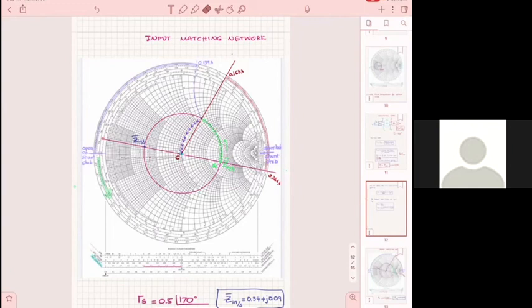That's why, moving in one direction or another, it's a good thing in practice to always keep in mind which direction you're moving. So on the same chart, you don't mix directions. That will be a mistake. But if you were to go into the opposite direction, as long as you stay consistent, your matching solution is going to be correct, but the lengths will be different. So you're going to have a different matching network, but it's not necessarily going to be wrong. It's going to give you the same reflection coefficient.